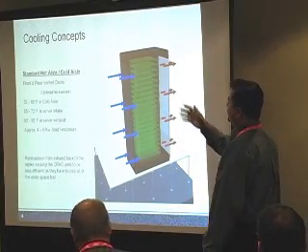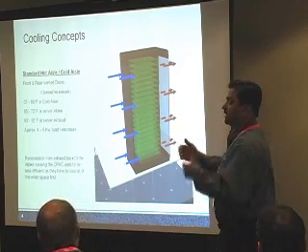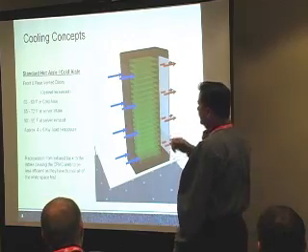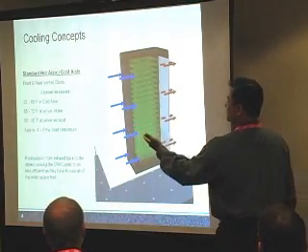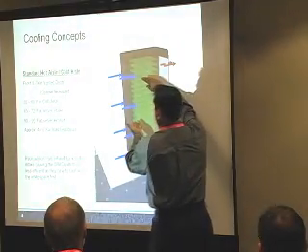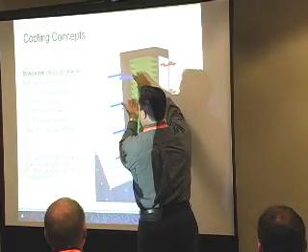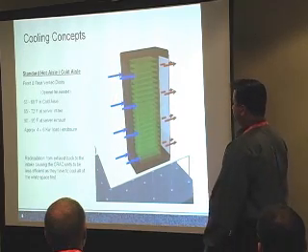Standard hot aisle, cold aisle is front and rear vented doors. Optional fan assisted, but you still have a standard hot and cold aisle pulling a horizontal flow. So typically you see 63 to 68 in the cold aisle, 65 to 72 at the server intake, typically at the top half of the cabinet. It might be cool in the cold aisle, but if you measure right inside there, there actually is an increase.